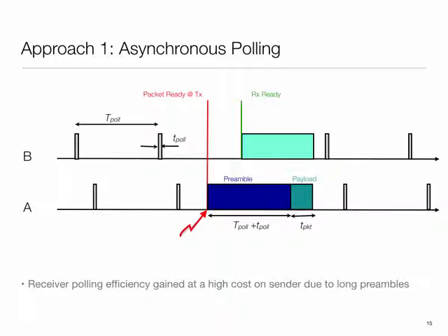Okay, and there are many ways you could imagine doing it. So one very common way is the following: packets have a preamble at the beginning, and that preamble is used by the receiver to lock onto the signal, to figure out what frequency you are transmitting the bits at, and then match that.